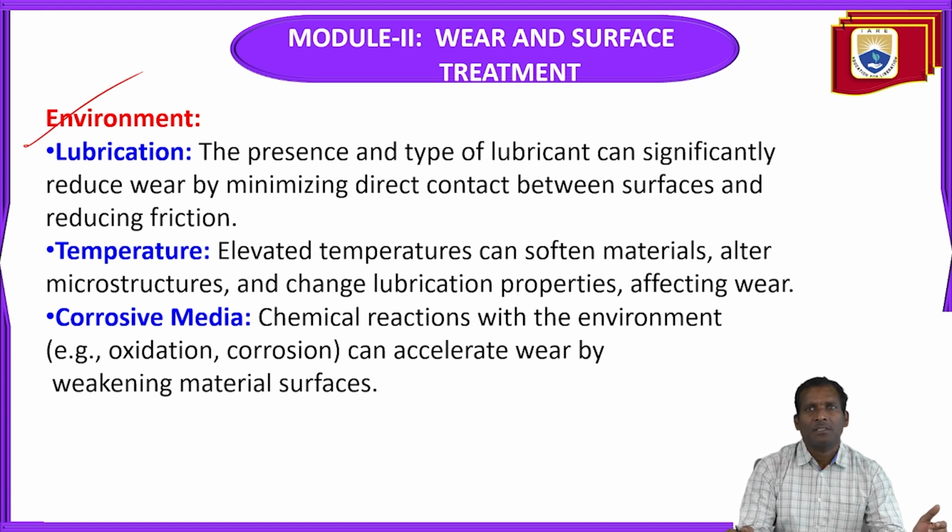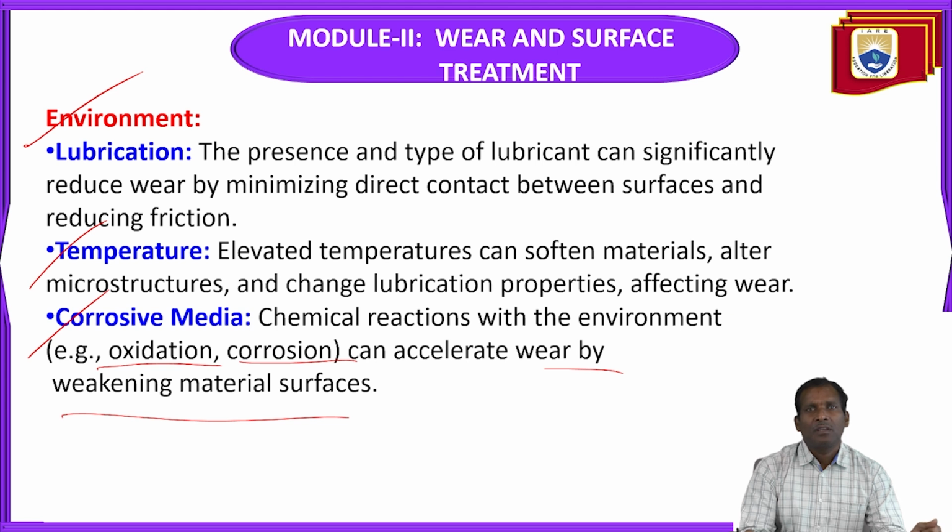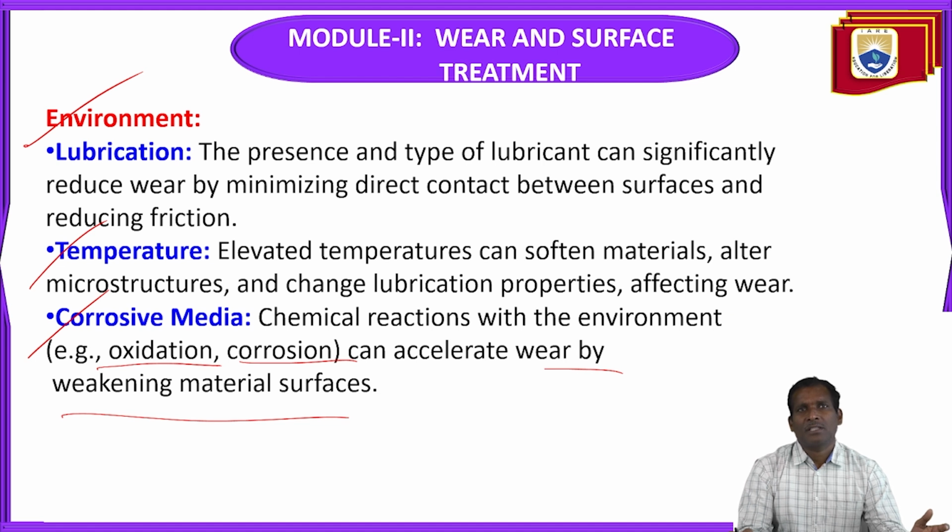Elevated temperatures can soften materials, alter microstructures, and change lubrication properties, affecting wear. So next, corrosive media. The chemical reactions with the environment, that is oxidation and corrosion, can accelerate wear by weakening material surfaces. Corrosive media, temperature and lubrication, these are the environment factors.